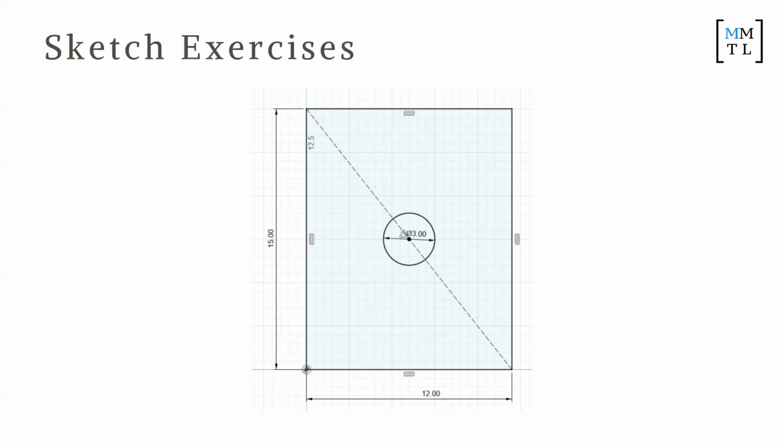Red lock means that your sketch is fully defined, but all the lines are black, it's good. After you finish the sketch, you can click finish. Then what you should see is the red lock on the left side, and that means the sketch is fully defined. All dimensions, you know exactly where everything is.